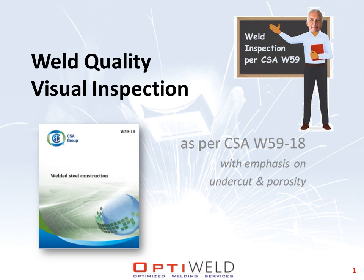I see on the Canadian Welding Bureau website that there are 5,058 companies in Canada certified to CSA W47.1 who typically use W59, in addition to another 519 companies from outside Canada, so this standard does get a lot of use. Over the years, I've seen mistakes made during weld inspection from ignorance, criteria confusion, and yes, sometimes laziness. So my message here is to inspect to the relevant acceptance criteria and don't accept defective welds, or mark not perfect but acceptable welds with yellow markers for repair.